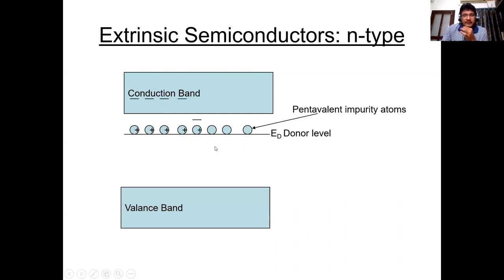So in semiconductors, there are two kinds of charges, mobile charges and immobile charges. Mobile charges are moving and take part in current conduction, and immobile charges are not moving; they create the space charge. In an N-type semiconductor, we have more electrons, but we don't have more holes. We will have some due to intrinsic excitation, but the number is very, very small.